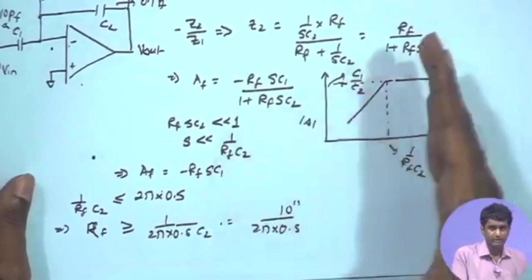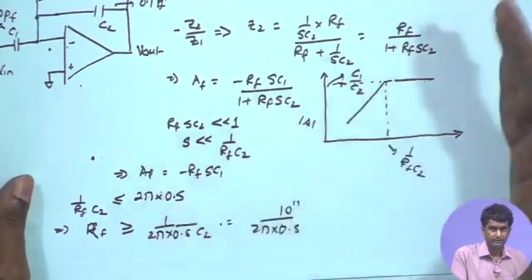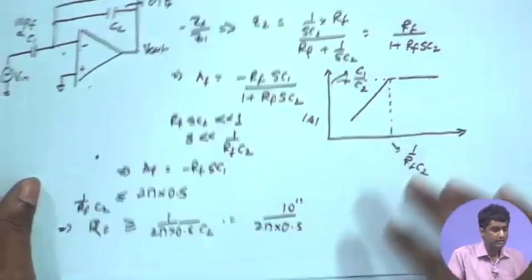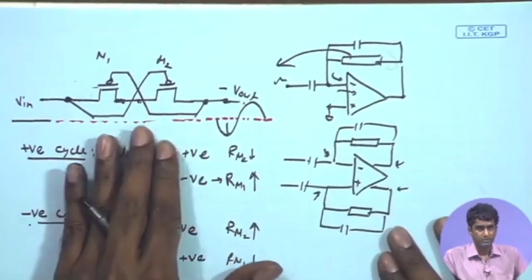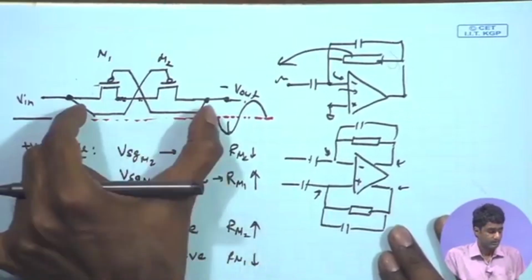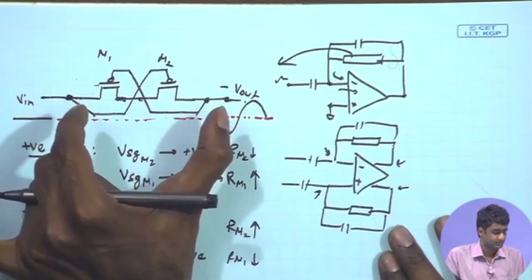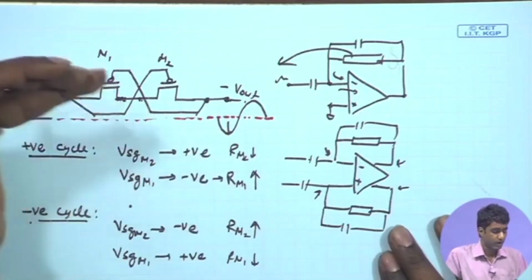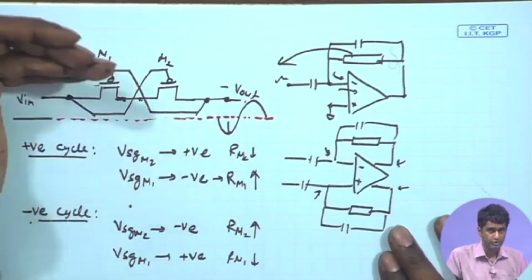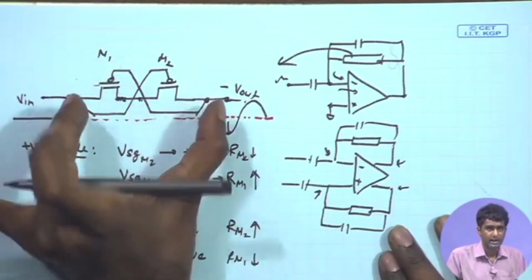So that is not a very well controlled value, it can vary by a factor of tens or even higher. So it will be good to have some kind of tuning option or calibration, so that this large value of resistor is calibrated or tuned as per requirement. So we need to have some post silicon calibration or tuning option, so that it is controllable or adjustable.